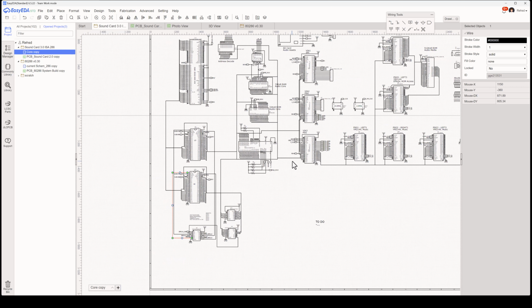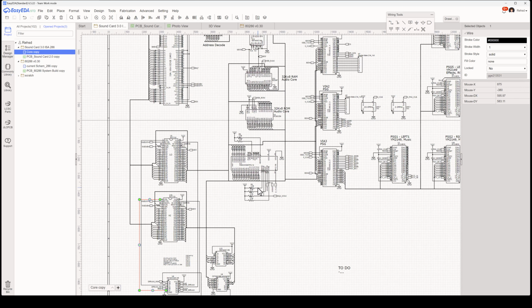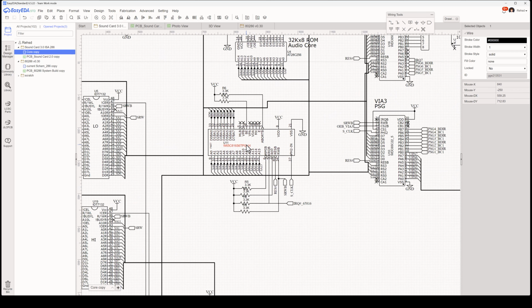And then off to the right, I've got the rest of this that really hasn't changed too much. I do have on my 65816 processor the interrupt line here, which I pull high because when it goes low, that's triggering that interrupt. It is an active low, IRQ bar. This is that signal that I'm going to kind of cheat on and take one of those DMA signals on my ISA bus and use that to pull this low.